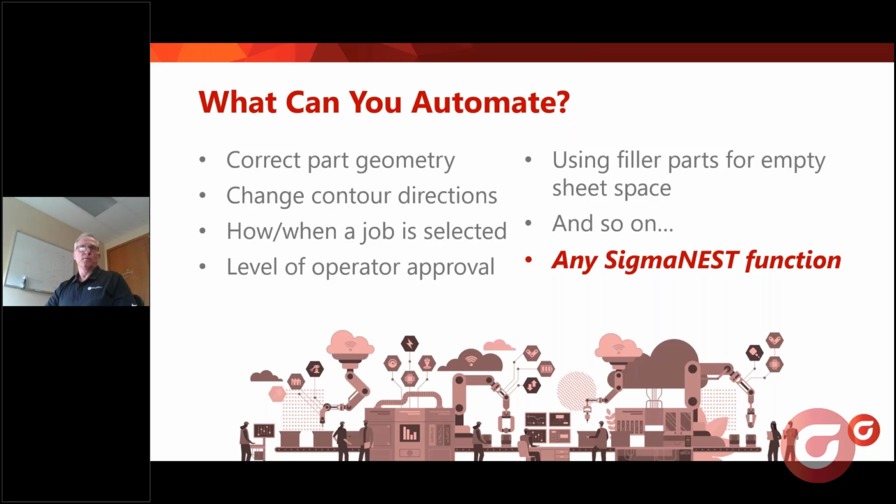There could be business rules such as nesting based on size. Certain contours on the parts have to be processed on a router, for instance. They could have to be processed in a reversed climb milling scenario where the console can be programmed and interrogating parts to set all of this up in preparation for nesting.